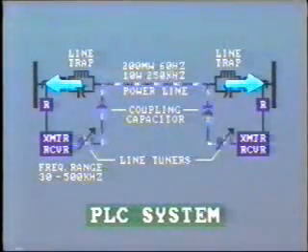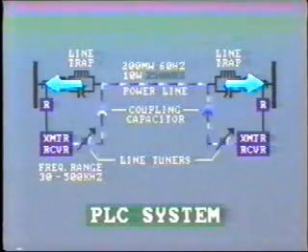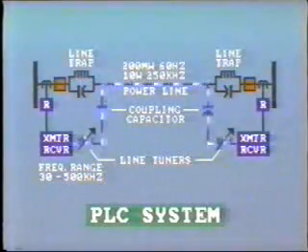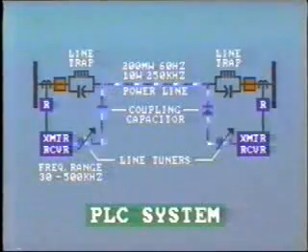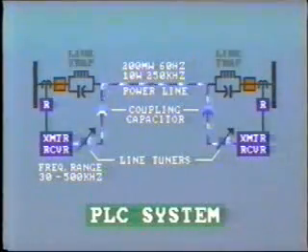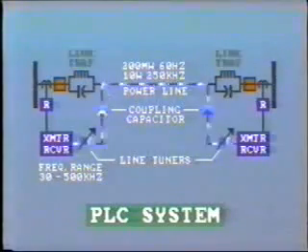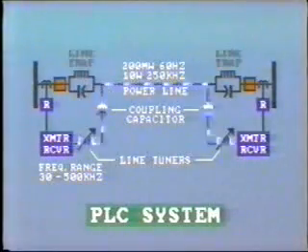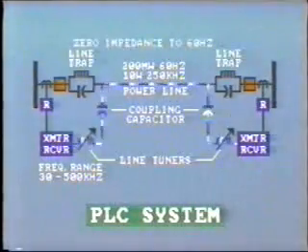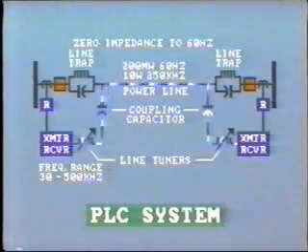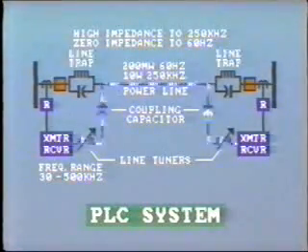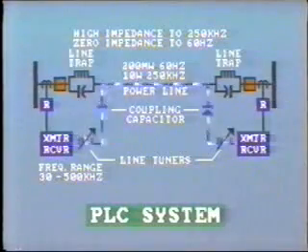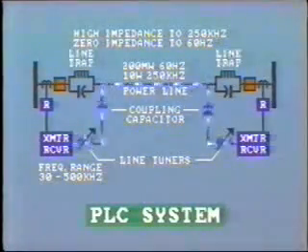How can we prevent it from escaping into the bus and the power network at each end? This potential problem is resolved by fitting line traps in series with the line at each end to block the flow of high-frequency current, that is, the signal. The line trap consists of a capacitor and reactor in parallel to form a resonant circuit. This is tuned to provide zero impedance to 60 hertz current, but to provide a very high impedance, almost open circuit, to the 250 kilohertz signal.